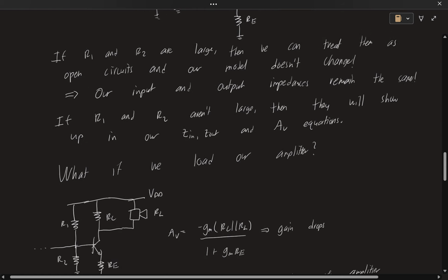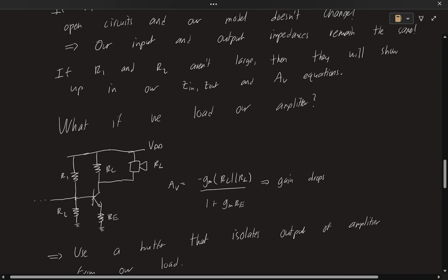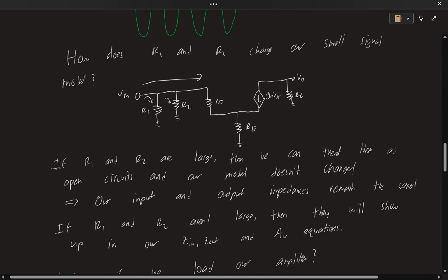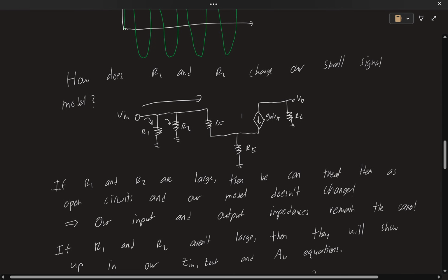So what happens here? All right, the next thing I'm going to talk about is loading. And the reason I bring up this R1 and R2 biasing is because one of the assignments on the module is talking about making an amplifier stage that has a certain gain, a certain input resistance, and I believe a certain output resistance. Okay, and input is going to be pretty large. That's great, but you'll realize that you can get the right gain out, but then you're not going to be able to match the output resistance for typical values of R1 and R2.